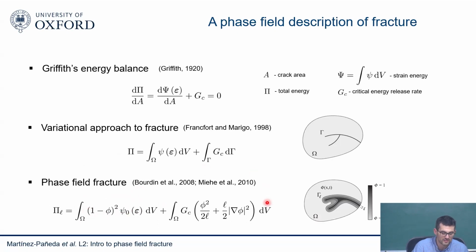The other thing is that it's a non-local continuum damage mechanics model. And that's the issue with continuum damage mechanics modeling: first of all, it doesn't link to fracture as Griffith does, but also normally models are local, which means they are mesh dependent. Here, you get a non-local continuum damage mechanics model where you have a gradient, and because you have a gradient, due to dimensional consistency, you bring in a length scale. And this length scale plays a role in multiple ways. We'll discuss them later on.